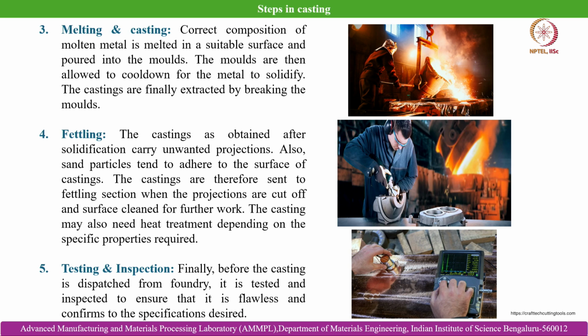And then fettling. So what is fettling? Basically, like we have discussed in the last class also, a typical casting deals with the mold gating arrangements, and also runner, riser, and also the pouring sprue and all. So these are basically the analogous parts which are non-functional parts after solidification. Of course, they are the functional parts during the melt preparation process.